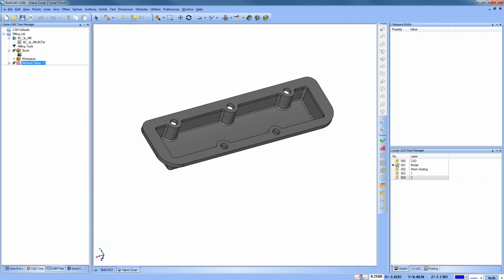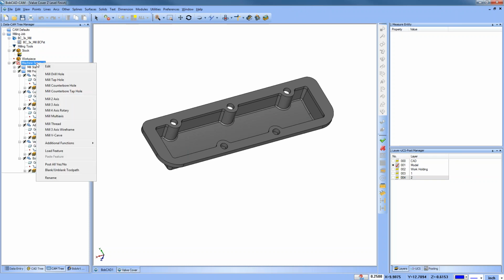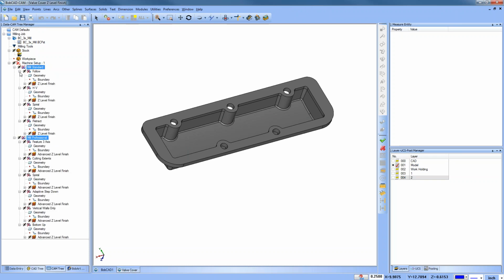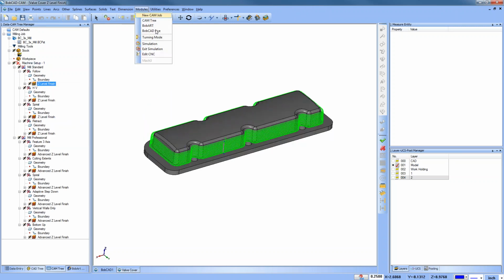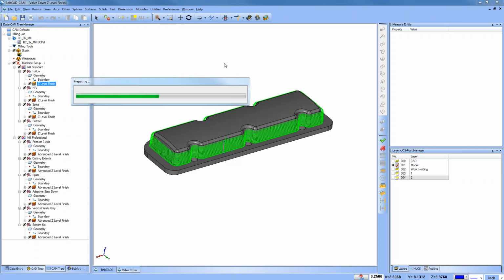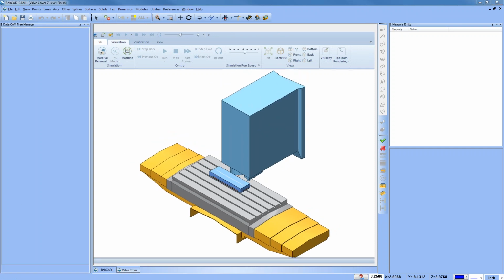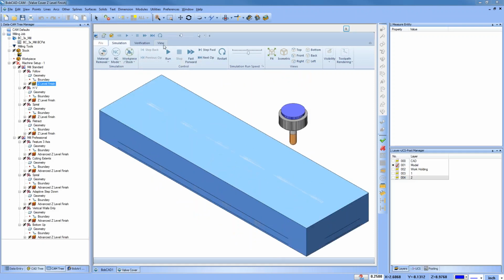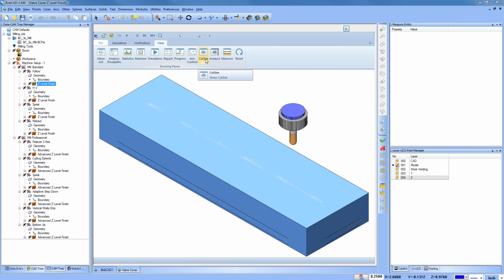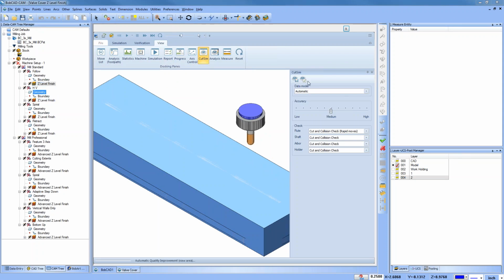But as far as keeping track of the in-process stock, how you handle that is with a special little feature here. So let's go ahead and show you real quick. I got a lot of toolpaths that I want to review with you guys, but where you're going to find this is in simulation, okay? When you guys go into simulation, did you know that you have the ability to save out your stock? You may not have known that, so let me explain how that works, okay? If we go to the Cut Sim tab here, okay, and then it's this button, this one right here, that's the one. This is the button you want to press.